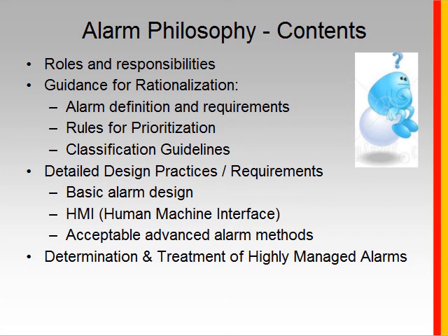We're going to talk in particular about how to treat highly managed alarms. Within the ISA 18 standard, highly managed alarms is the term that's used for safety alarms. It's alarms that require special attention, basically.